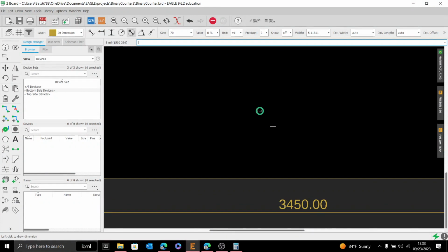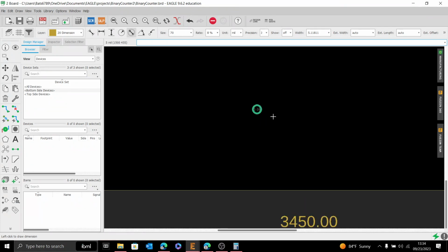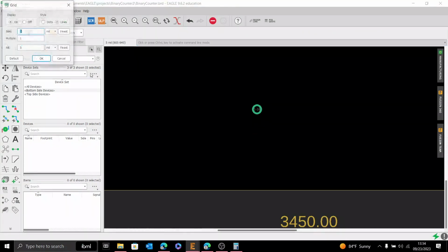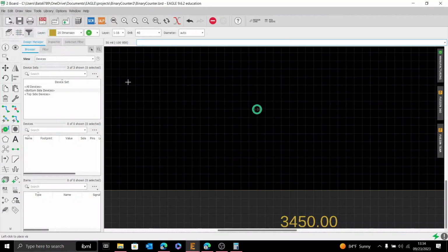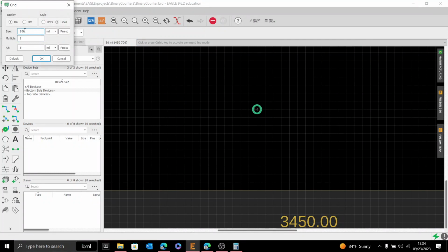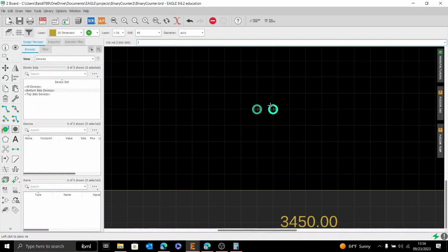So let's see, 2.5 millimeter mounting hole, 6 inches apart. And the pinholes are 0.1 inches apart, which is 100 mils. So we're going to come along with this via here. My grid's a little small now. Let's put you back to 50. Or technically, we could do 100, and then we know that we just need to stick them like this. So since I'm using this for reference, there are 8 of these. So we're going to go 8 across.